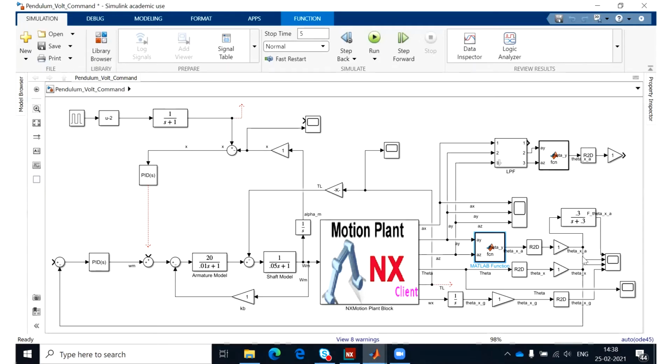But one of the problems we had is that the acceleration, when we get it here in Simulink, is very noisy. So we are working on reducing this, but this is actually due to some of the numerical solution of the NX. We need to investigate that more, but for example, because the wheel is not completely a circle, it has some corners, it could be because of that and some other reasons. So Hamid has done some improvement in the NX model. It used to be more, but it is still there. When I simulate it, I will show you that we have noise here.